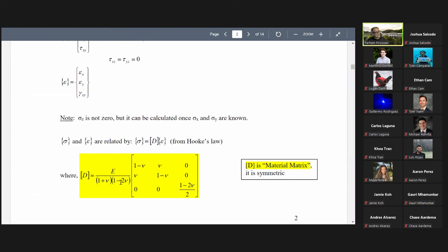Sometimes you give Poisson's ratio of 0.5 and the system can't proceed because of this situation. As you see, we run into a serious problem. But in almost all cases, Poisson's ratio is never 0.5. It is usually a number between 0 and 0.5, less than 0.5. But 0.5 itself causes problems here.